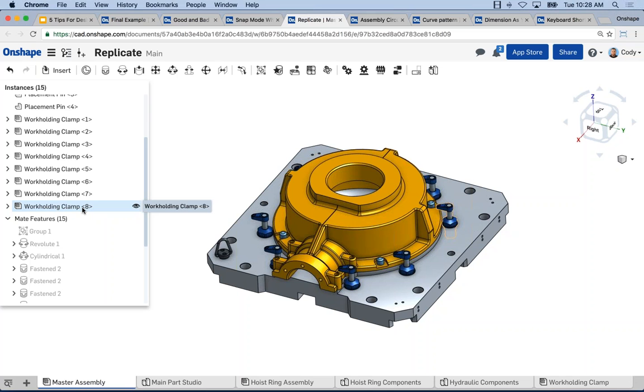Now, of course, this is a subassembly. If I were to change the subassembly, then in all instances, it would update, but it's not a single feature in the feature list. So I can delete one, for instance, and not have the others. Okay? So a big tip: any of those scenarios where I'm inserting a dozen bolts, for example, and I have this same hole in all these different places, very common scenarios.